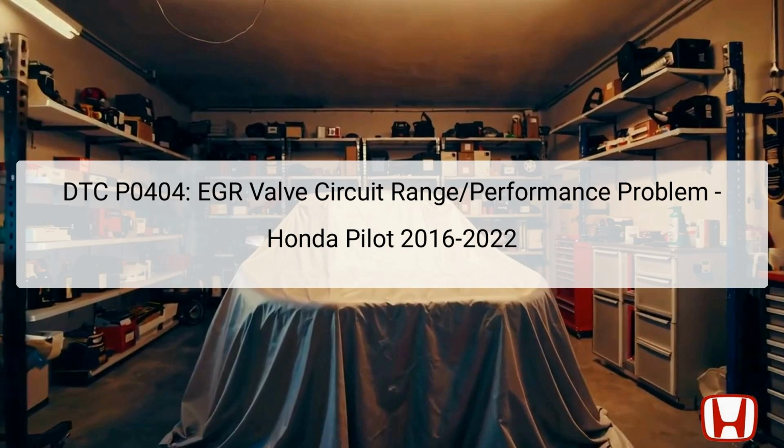The EGR system plays a crucial role in reducing emissions by recirculating a portion of the exhaust back into the engine's intake. When the EGR valve is malfunctioning, it may not open or close properly, leading to performance issues or increased emissions. Often, diagnostics for this issue start with confirming the DTC through a specialized Honda Diagnostic System, HDS, which reads parameters and helps pinpoint malfunctions. It is essential to understand the significance of the EGR system in maintaining engine efficiency and environmental compliance, especially in today's automotive landscape.